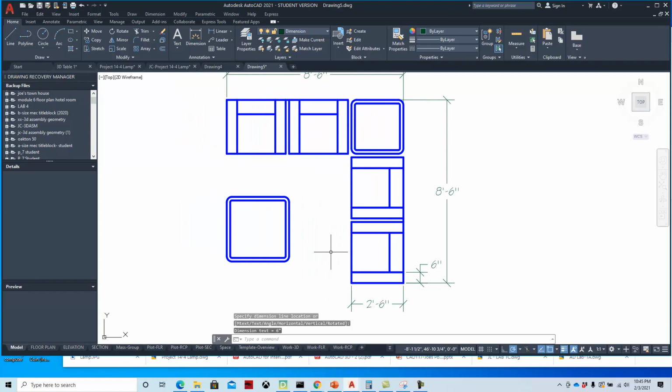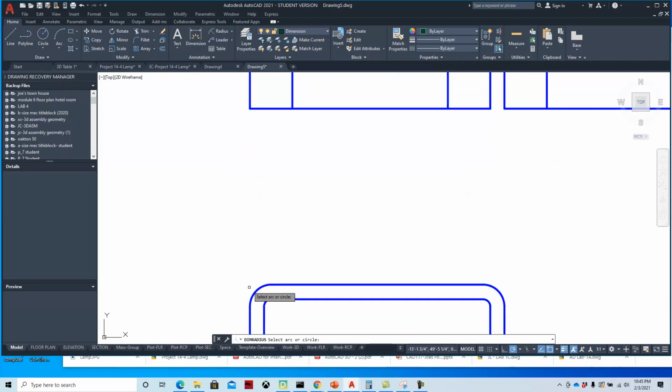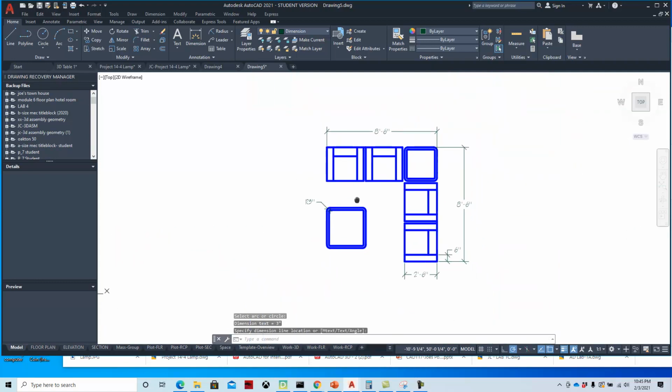I don't think we need to have me put all of the dimensions on here. Linear dimensions will all come in pretty much the same like that. And then radial dimensions, you'll choose a radial dimension. And then you can just bring it over to the edge, click on that, and drop that in there. Once you have the object drawn and dimensioned, we'll save that file.